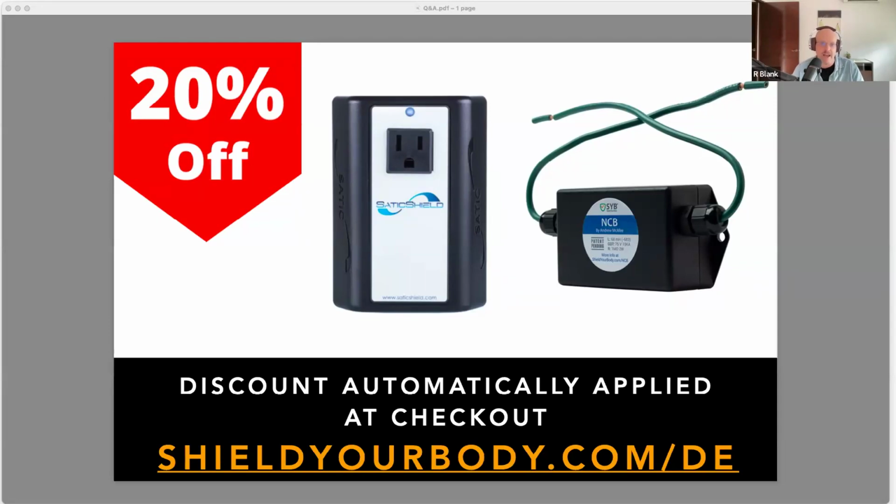BD, it looks like you have something to add here. I do. One of the major culprits of dirty electricity is wiring errors. And again, I don't mean to beat this up, but the best way to fix something is not buying a bunch of filters. The best way is to not have dirty electricity, right? There are 9 different variations on wiring an outlet. Only one is correct. I have never seen a home, new construction, that didn't have at least one outlet where the neutral and the ground were switched, bonded, etc.